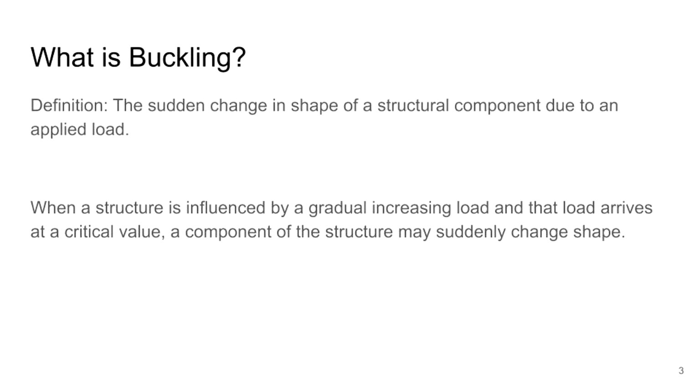If the buckled member is a part of a larger assemblage of components, such as a building or a bridge, any load applied to the buckled part of the structure beyond that which caused the member to buckle will be redistributed within the structure. As an example, some aircraft are designed for thin skin panels to continue carrying load even in a buckled state.